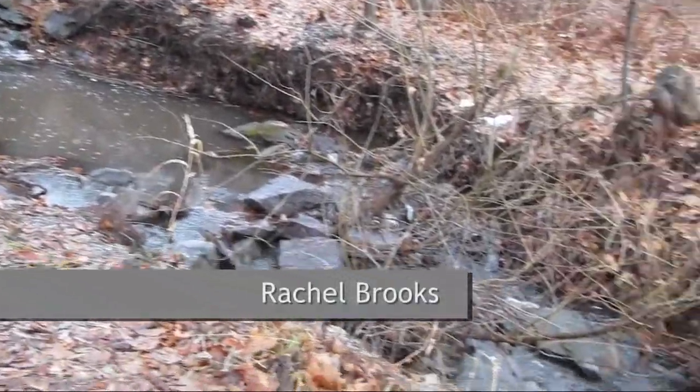This is one location for an infiltration trench. This trench will be filled with karst limestone, creating a reservoir for water to soak into the ground easier. It will also provide high pollution removal. A sand filter will be located here and will be our best method for removing solids and vehicle pollutants from parking lot runoff. A retention pond will be located here.